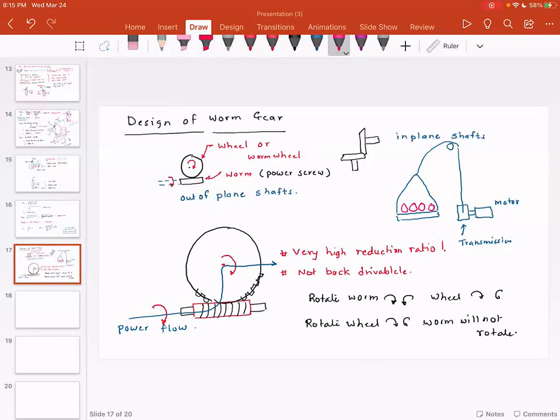All of a sudden, when the load is in the middle, the motor loses power. So power drops. If you use bevel gear, spur gear, or helical gear, the load will drop down because of its self weight. The load will drive the motor. But if you have a worm wheel, imagine you have a wheel here and a worm here, then the motor will not be back drivable.